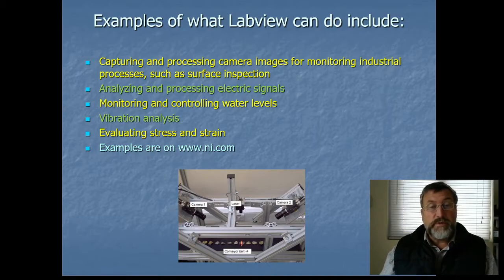Another example we've got down here is evaluating stress and strain. So what we could do with that would be, we have strain gauges. I don't know if anybody has a great deal of experience of using strain gauges, but they're very sensitive little pieces of material which you mount onto objects. Then as the object undergoes strain, when stress or a force is applied to it, you can measure the strain. Actually, I've got a little example in this presentation of that being used. That is used very commonly in evaluating finite element models, because you can do a load of finite element modeling, but there's no guarantee that the models you've got are actually valid.